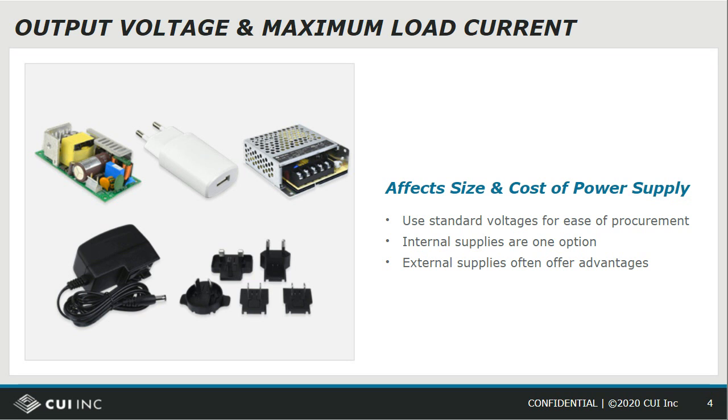An external supply, in contrast, will have some voltage error due to the typically longer DC output cable. The current times the impedance of the cable will create a voltage drop, and that voltage drop changes depending upon the load current being drawn. With external supplies, low tolerance output voltage can be compensated for by putting either a low dropout linear or switching regulator in your product, or a more traditional, perhaps isolated switching converter inside the product to convert the low tolerance external supply voltage to a tight tolerance internal voltage.